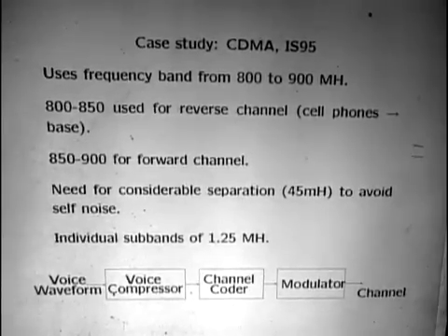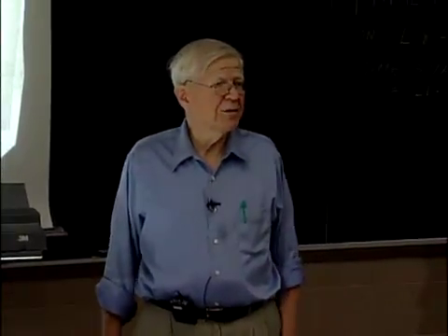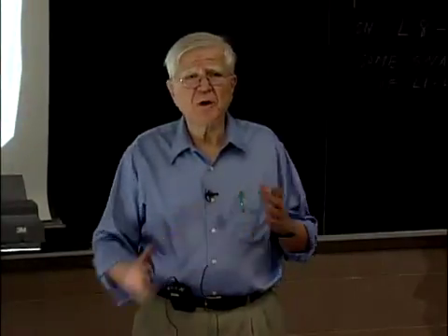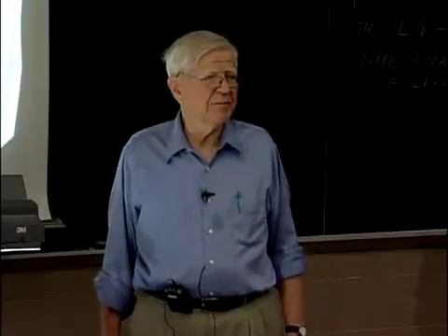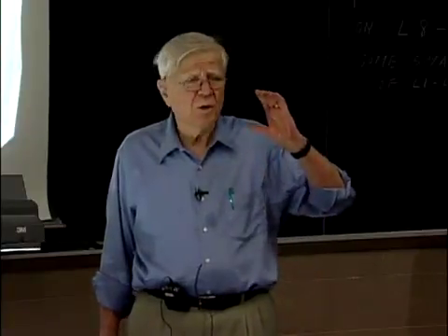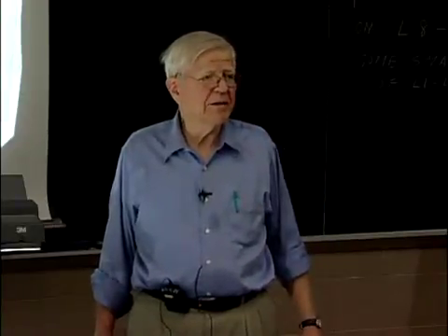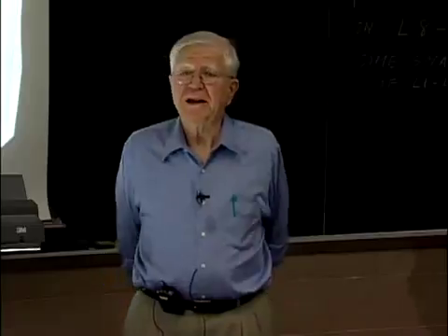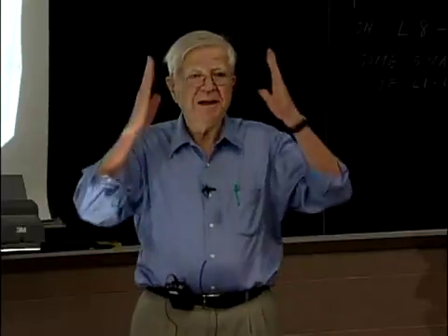If you think for just a minute about the power levels at your sending antenna, either at the base station or at the cell phone itself, and then you think about how much power you're receiving, you see there's an enormous difference between these two, because things get attenuated enormously after they get transmitted. So what you're trying to do is to filter out what you're sending, which is an enormously high power, and you have to filter it out by enough so that it doesn't clobber what you're trying to receive, which means you need very good filters. And how do you build very good filters? Well, it's a lot easier to build good filters if you're not trying to make them cut off immediately.